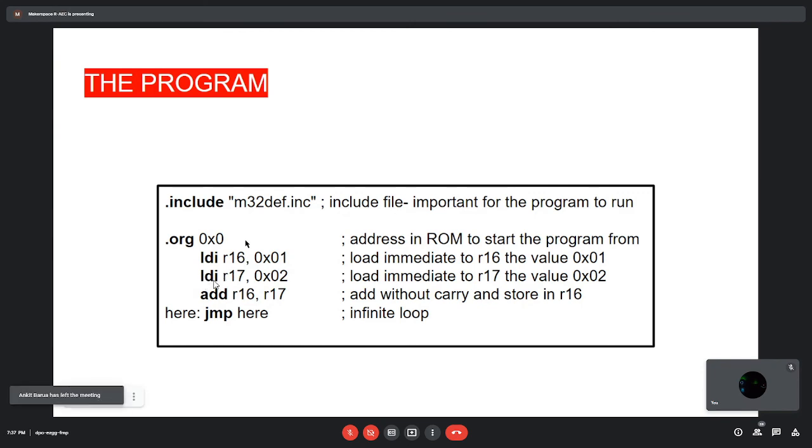Then we have another LDI, load immediate. We are loading immediately the value 0x02 into the R17 register. So we are choosing two registers and storing two numbers. Then we are adding the two numbers, R16 and R17. The trick here is that R16 and R17 are added and the total value is stored in R16 itself. Initially R16 had 1 stored, but after this step we will get R16 as 3, because 2 plus 1 is equal to 3.